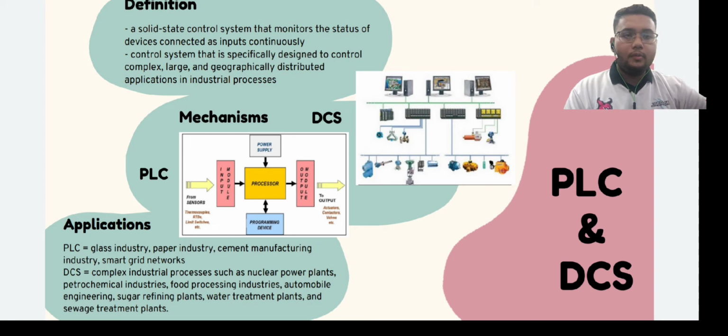Based on a user-written program, a PLC operation is divided into 4 steps. The input scan first will scan the state of all input devices connected to the PLC. The user-created program will be executed during the program scan. During the output scan, all output devices connected to the PLC are energized and de-energized. Internal diagnostics and communication with external terminals are included in the final step, housekeeping. In a loop, all steps in the PLC operation will be processed continuously.